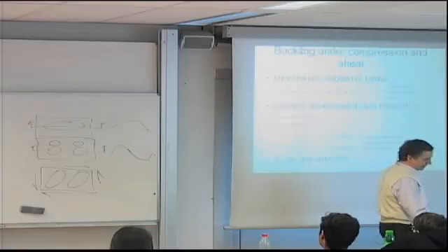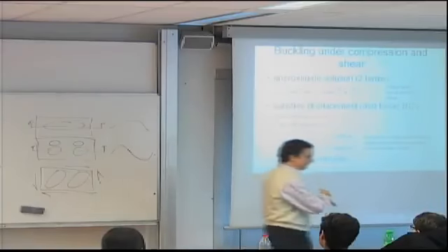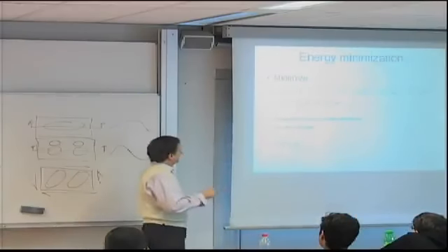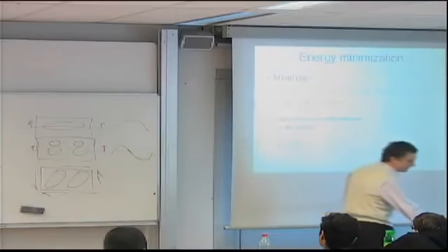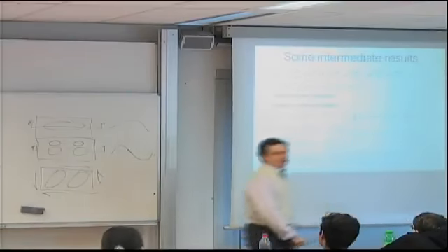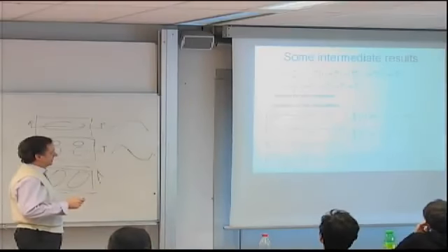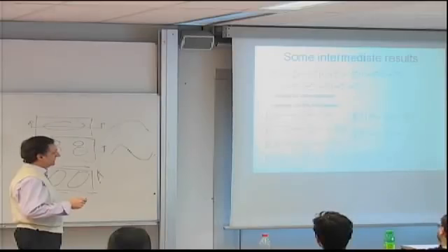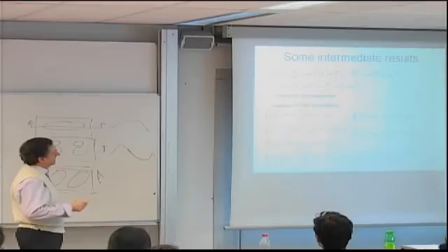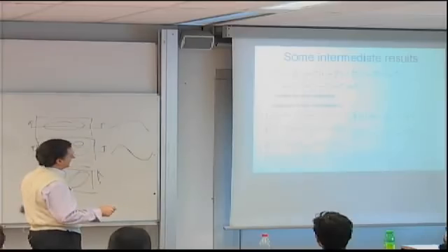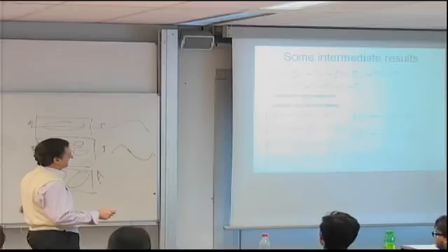So I now have to take this W, take all the derivatives that appear in this energy expression, integrate, and hope for the best. For example, dW/dx squared will involve a sine squared, and the sine squared, as you know, can be written in terms of cosine of twice the angle. So sine squared x and then the cosine and the sine squared y terms are here, and so on. Once you then carry out all the integrations, every single term in the energy expression is shown here,